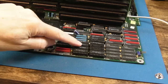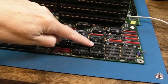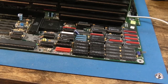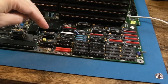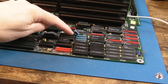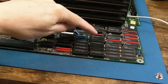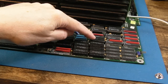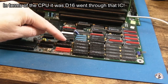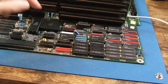One thing of note, I went through all the RAM chips here, including a few of mine that I thought were faulty, they weren't. But yeah, two of his RAMs were faulty, so I've had to swap two out there. That won't have been helping matters, but there were a number of things, at the point where I just couldn't get this to boot at all. We had bad connection on two of the pins here, two of these RAM chips were faulty. We had a problem with this F245 here on data bit 0, the first data bit, and there was a wire that shouldn't have been there, I think on the F86, joining something somewhere crazy.